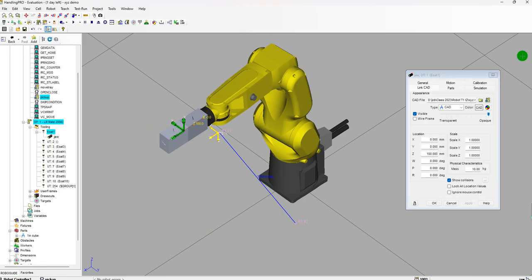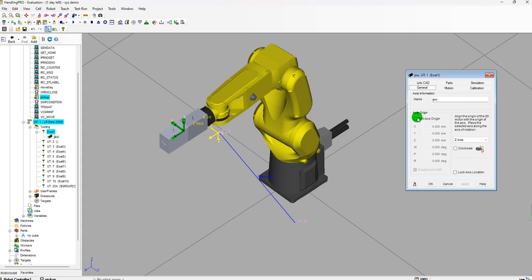I want to emphasize that for this draw part, the location here is XYZ, and in the general tab you also have XYZ WPR. That's not the location of the draw; it's the location of the servo motor or the force that drives it.